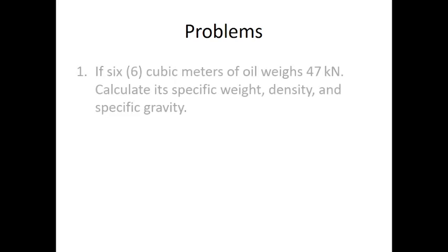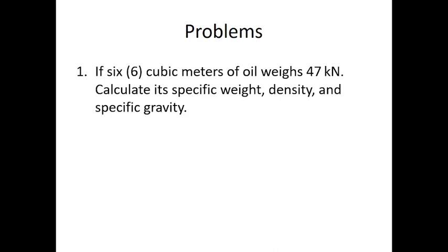Alright, so here's the first problem. If we have 6 cubic meters of oil weighing 47 kilonewtons, calculate its specific weight, density, and specific gravity. Let's analyze.